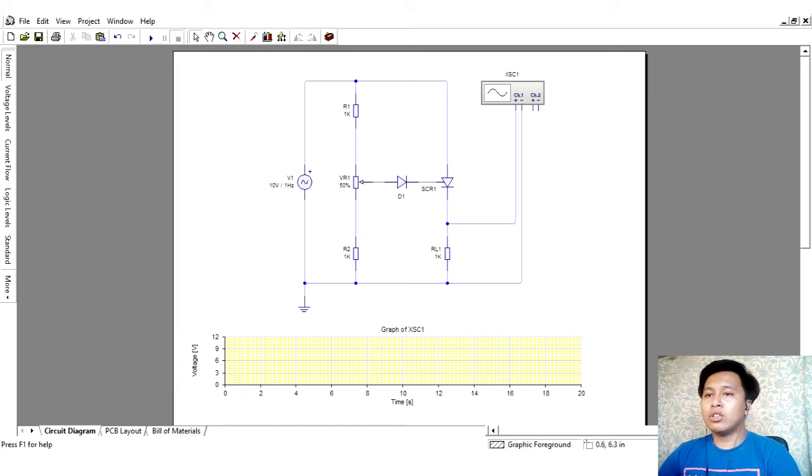If the triggering voltage is not large enough to trigger the SCR at 90 degrees, the device will not trigger at all, because the triggering voltage has maximum value at the peak of the input and decreases with the fall in voltage. This operation is sometimes referred to as half-wave variable resistance phase control. It is an effective method of controlling the load power.